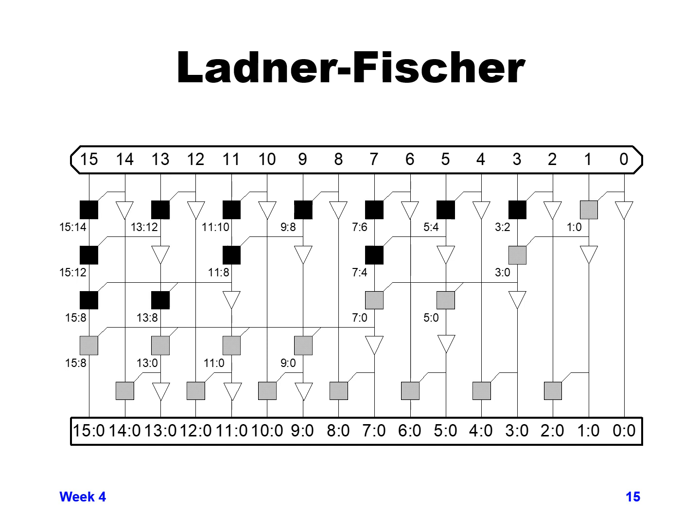And last but not least, in our tree adder designs, we're looking at the Ladner-Fischer design, which here is balancing again between two of the different parameters. But in this case, we're balancing off logic levels versus fan out. So the total number of receivers that a given driver has to drive.